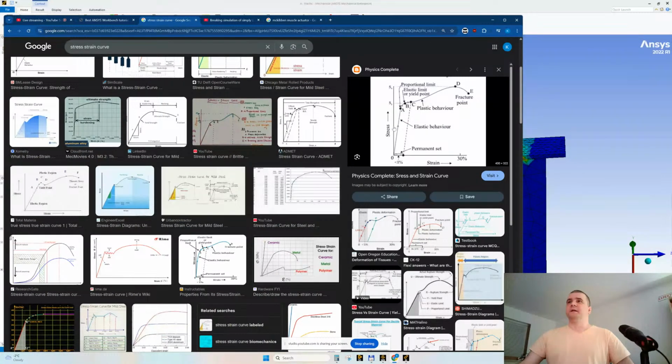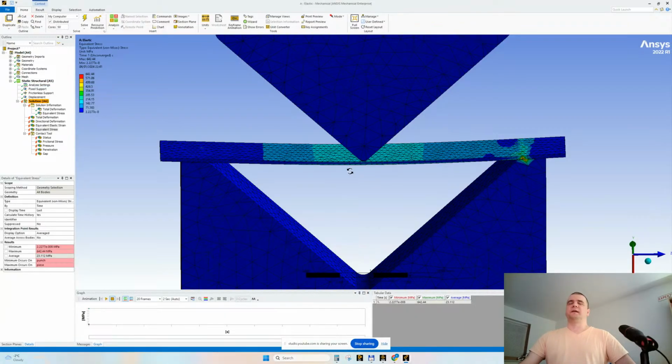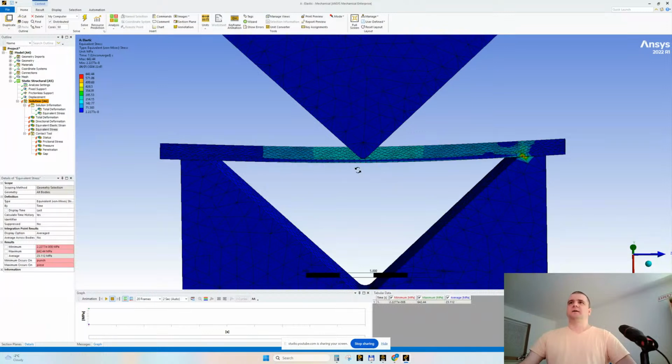We are here, but our load, our displacement is too much, and plastic deformation should occur. If we are going only through the elastic regime, we're forced to have a stiff material. If we have a stiff body, then the FEA cannot converge anymore. When defining plasticity, a certain softness occurs.